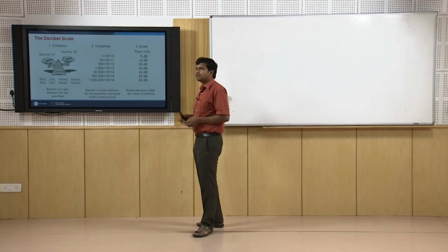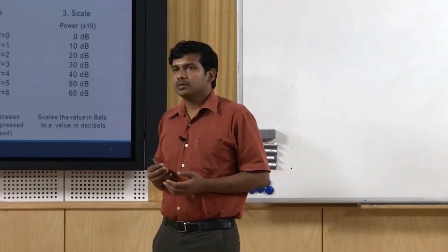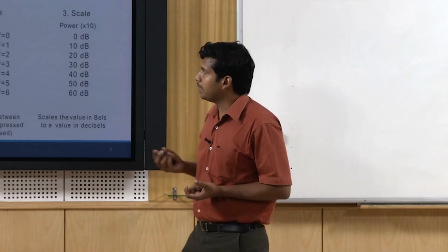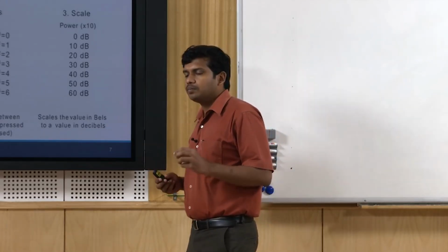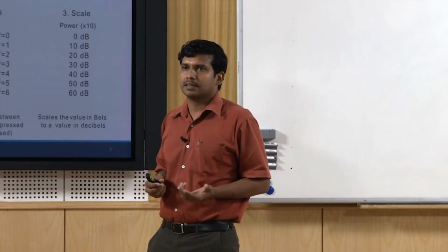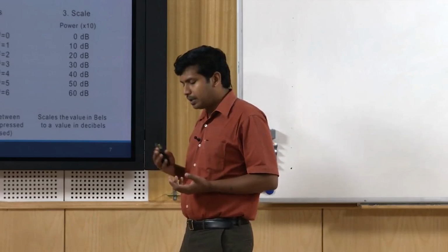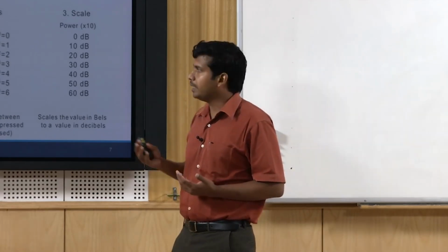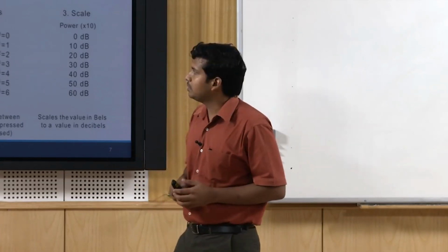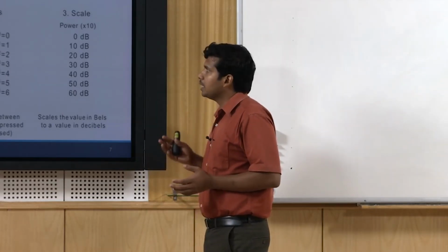So, how do we express sound? We always talk about sound pressure, sound levels. The moment you say level, it is a comparative term. Pressure is measured in pascals, but sound is not expressed in pascals. Typically you get to hear terms like 40 dB, 60 dB, 80 dB. So, these are levels, not the direct pressure value. So, why do we need to develop this?